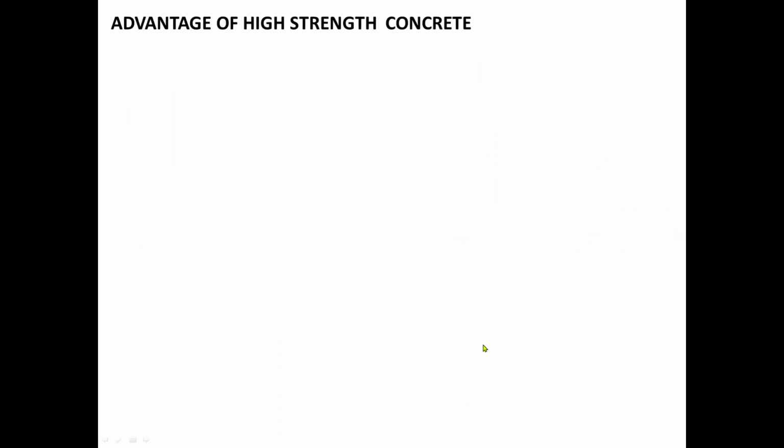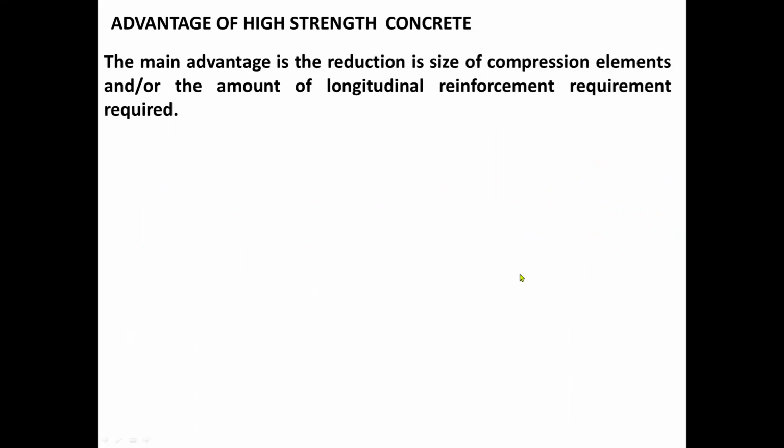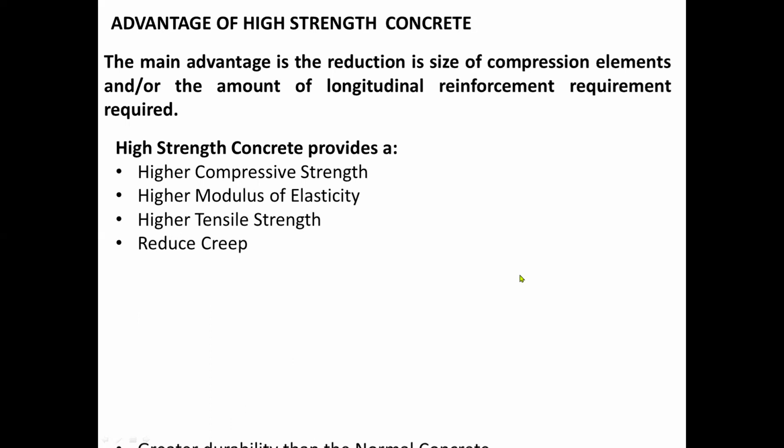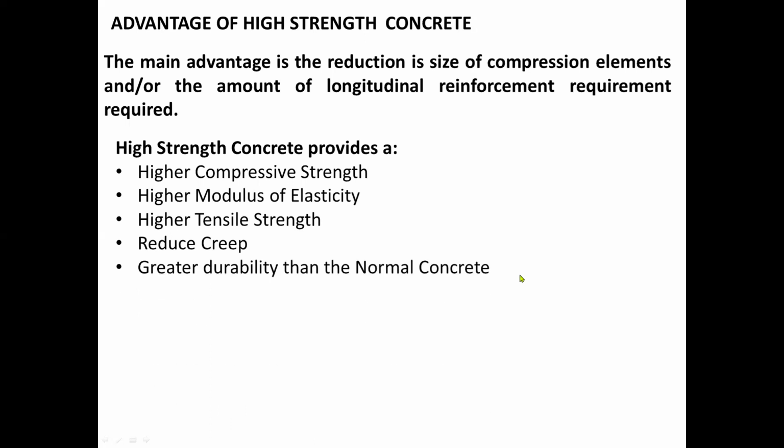For the advantage of high-strength concrete, let me enumerate them. First, the main advantage is the reduction in the size of compression elements and or the amount of longitudinal reinforcement required. High-strength concrete provides, A, high compressive strength. Second one, higher modulus of elasticity, higher tensile strength, reduced creep, greater durability than the normal concrete if we're going to compare them.